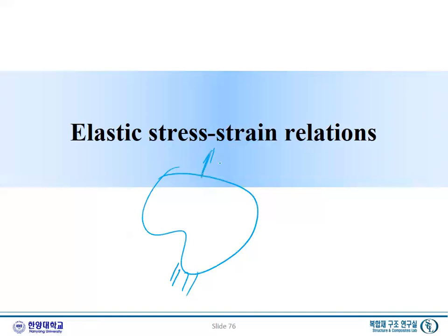When we have certain forces, certain geometry, there is something going on inside. So we pick a very small piece of material here, and we look at how much stress we have on each surface. That is a 3D version. 3 by 3, so 9, symmetric, 6 components.